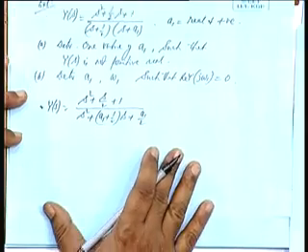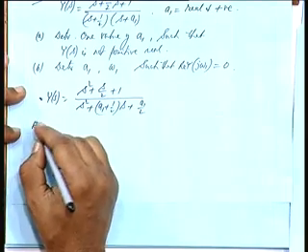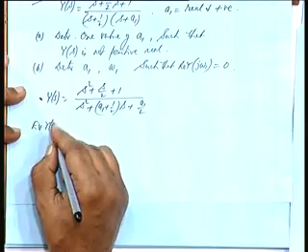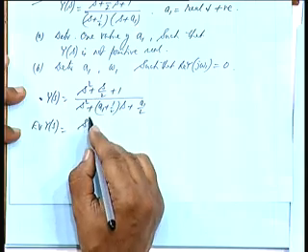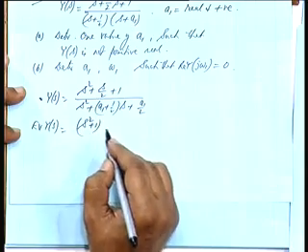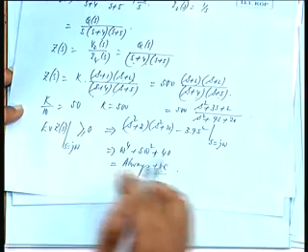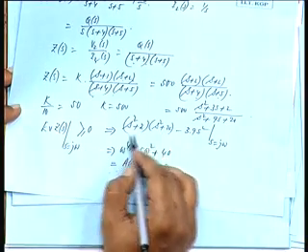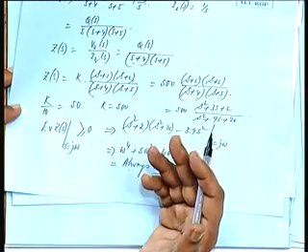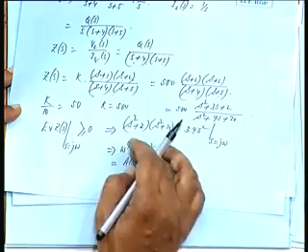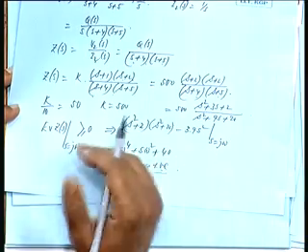So, even Z(s) or even Y(s), what is the even part? (s squared plus 1) into (s squared plus A1 by 2) minus this into this, half into (A1 plus half) s squared. Mind you, earlier also when we were considering even part, this m1 m2 minus n1 n2 that we derived, divided by m2 squared minus n2 squared, the denominator was always positive.